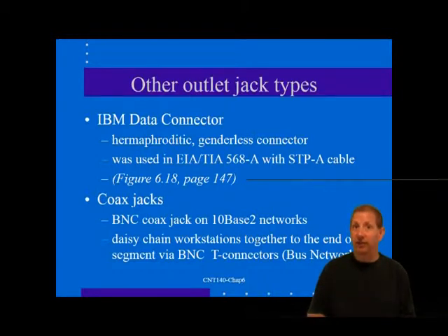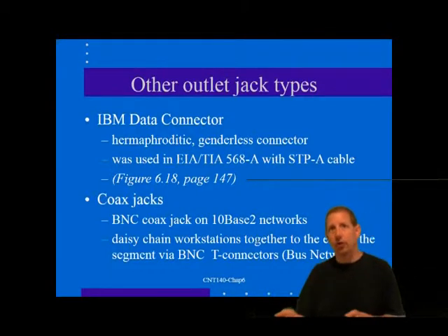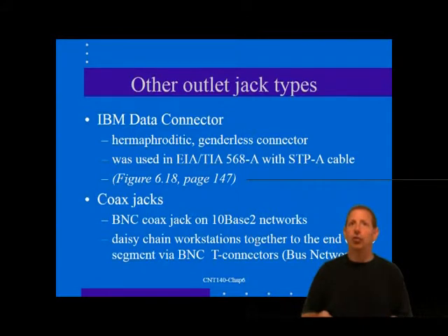The method generally does not allow an extra stub of coax from the tap to the workstation. Both cable sections must be extended all the way to the T at the workstation adapter. Each fixed 10-Base-2 coax outlet then needs 2 coax connectors, 1 for each cable section leading to the workstation. The customary outlet has 2 separate female BNC connectors on the faceplate, each connected to one of the 2 cable sections at the rear of the faceplate.